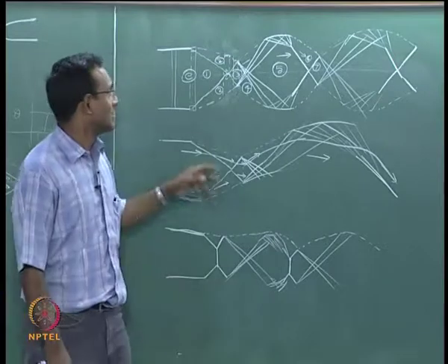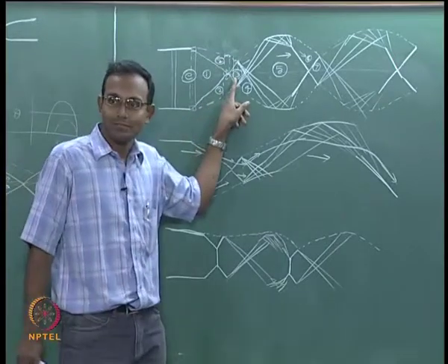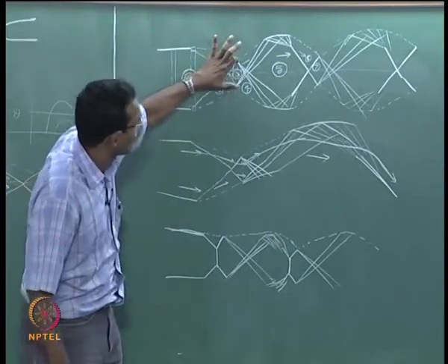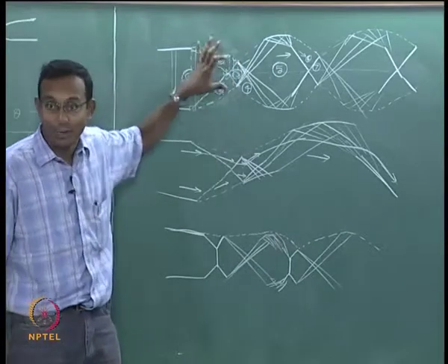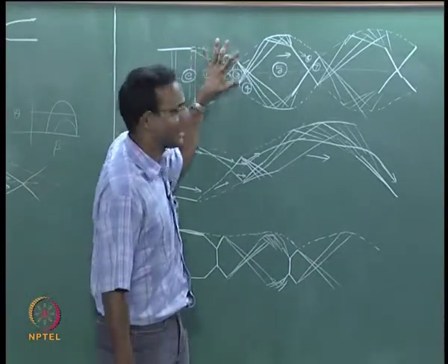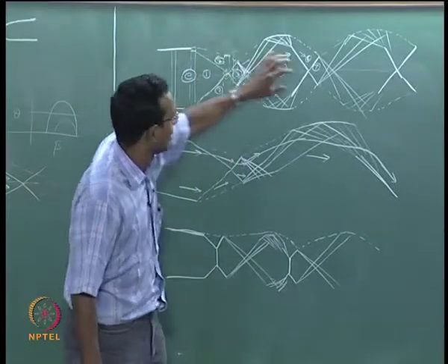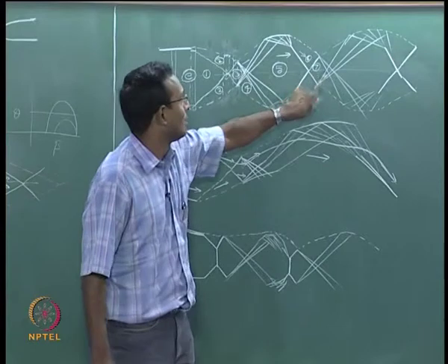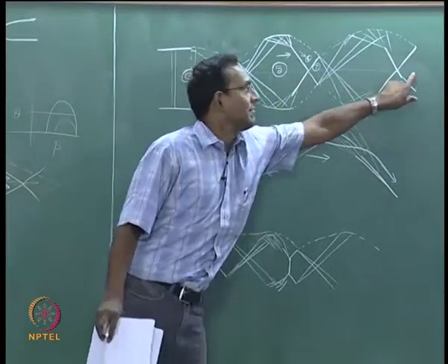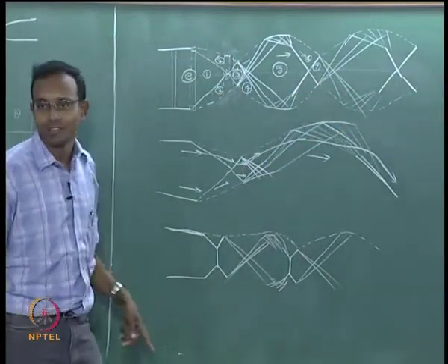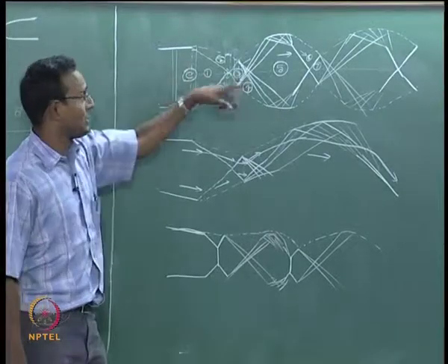Just go look at it taking off. You will see these diamond like structures just behind it which are glowing hot. Typically they will be glowing orangish yellow. This portion will be glowing hot, then the region 7 will be glowing hot, then 8, 9, 10, 11 will be glowing hot, and it just keeps going. The other regions will be cold.